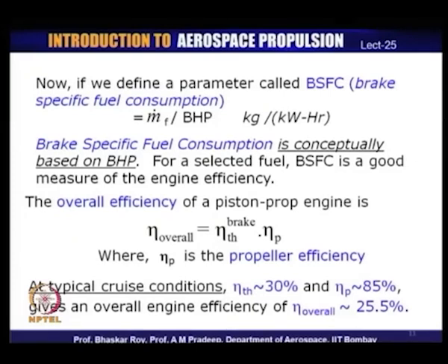Quite often in the engine specifications, you may not find the value of engine efficiency mentioned anywhere. It's more of a theoretical understanding by the designers, but engineers and operators quite often use BSFC as the measure of the engine efficiency.